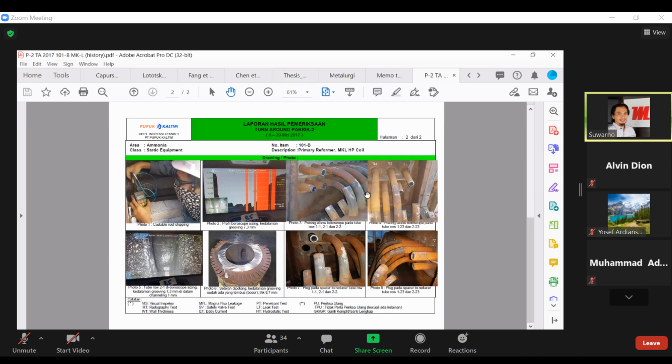To do so, you make an arrangement of tubing like this, and then in this process, people inspect whether there is any defect on the tube from the inside. It's not possible to do it easily when it is internal, right? So what we do is use a borescope, and you insert it inside, from one of the tubes somewhere here.